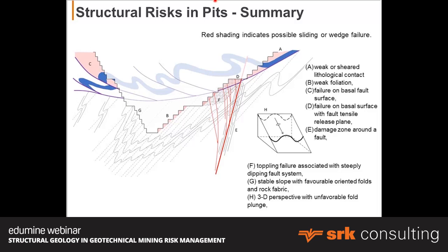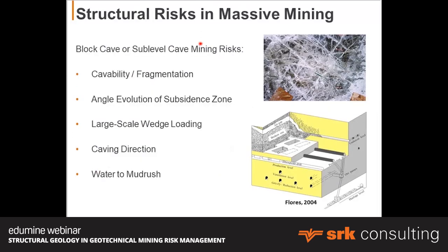Right, let's talk about massive mining. Particularly we're talking about block caving or sub-level caving type mining risks. The aspects we look at are cavability, angle of subsidence, large-scale wedge loading, caving direction, and mud rushes.